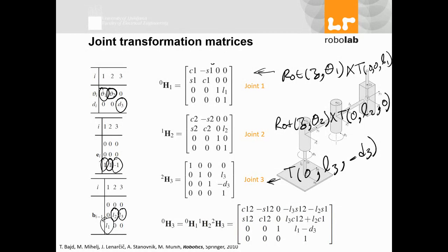So I'll stop here, and I hope that makes your approach more clear and you understand better. For any robot, I'll give you an assignment on this. For any robot, just follow the steps: reference pose, center of joints, coordinates for each joint, E vector for each one, then write the tables. You have to write variables, the E vector, and the B vector.